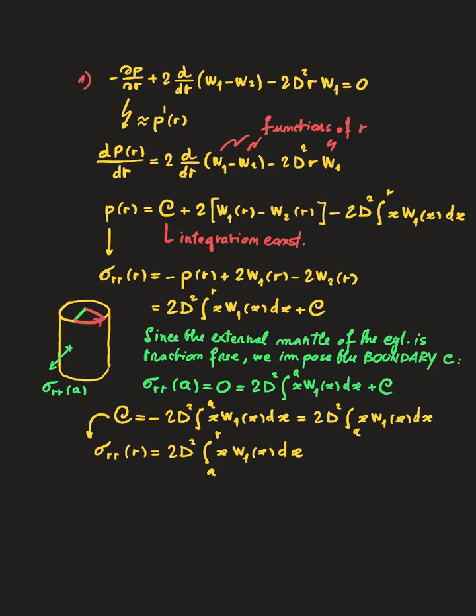This angle for a height of the cylinder equal to 1 is equal to d. This is the meaning of this d. It would tell you how much the upper surface of a cylinder of length 1 rotates with respect, for example, to the lower base, and this is the definition of amount of twist.